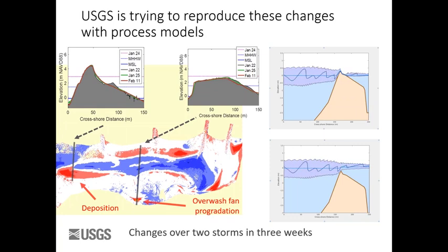No, well, it does have a sediment transport component in it, but what I'm interested in about SWASH is that it provides the wave asymmetry. So each wave is skewed forward, and so you can do the bed load transport, including the wave asymmetry. And there's another thing that I think is kind of interesting. We got off on another topic.